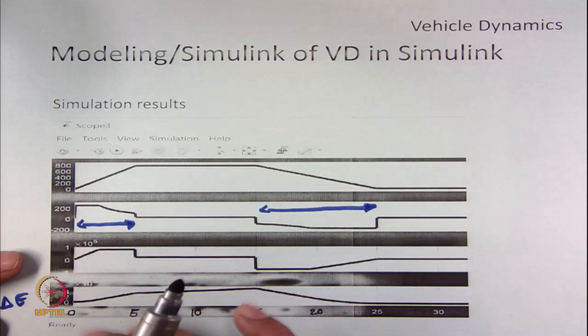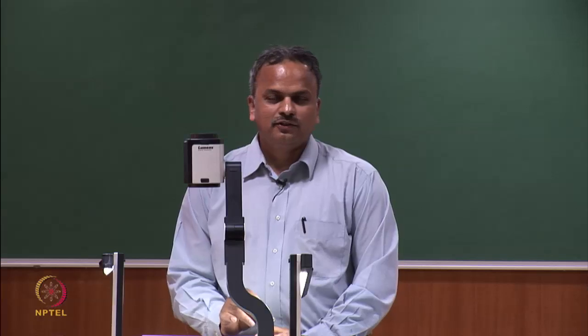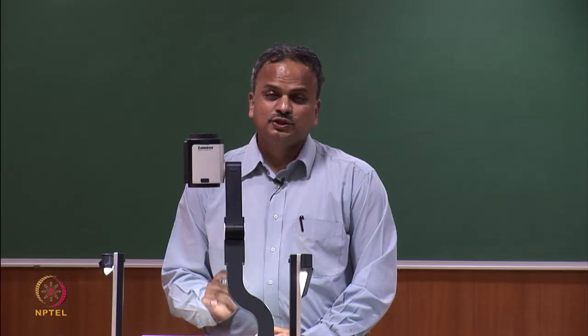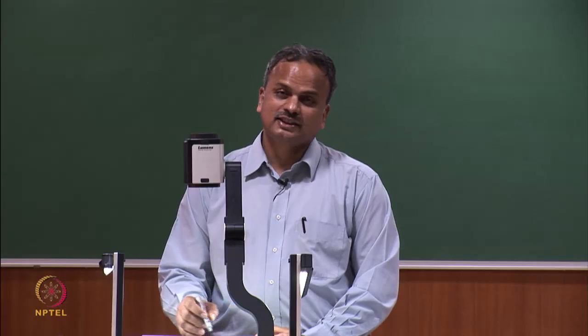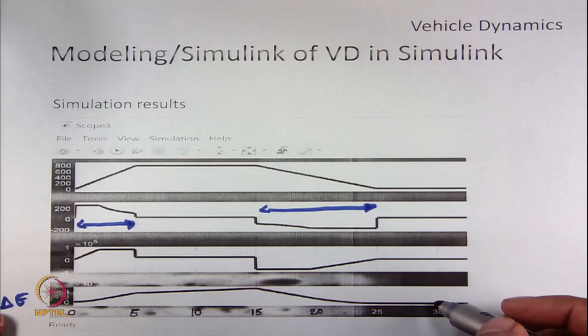One thing is very clear from these simulation results: if we know the battery capacity and we have to move from one place to another, we can choose the driving profile in such a way that we get maximum range. If we have periods of acceleration and deceleration in this fashion, we may not lose any energy of the battery, rather we gain something out of it.